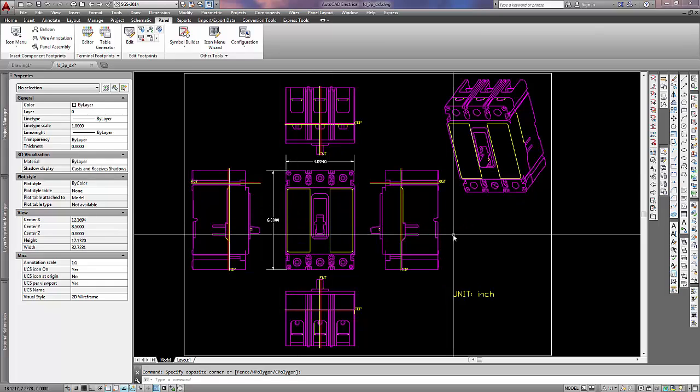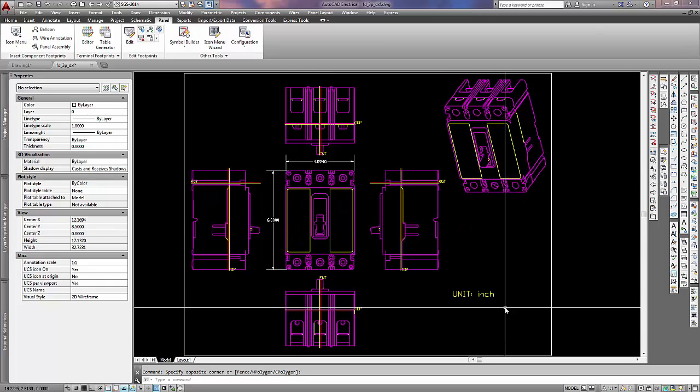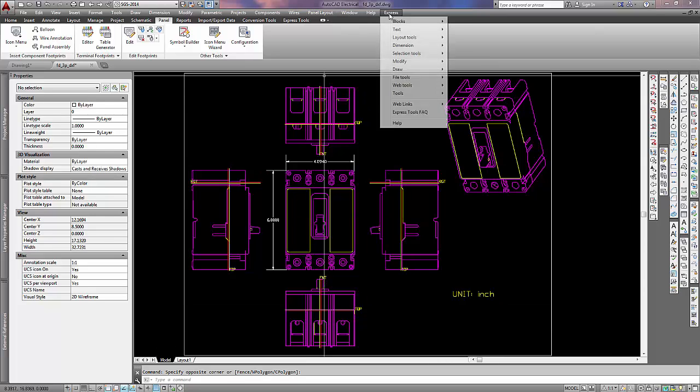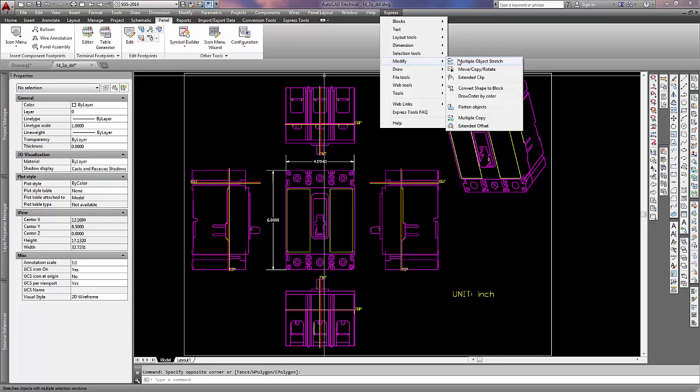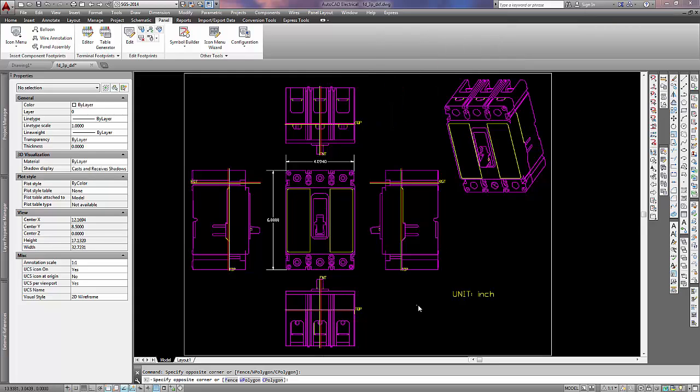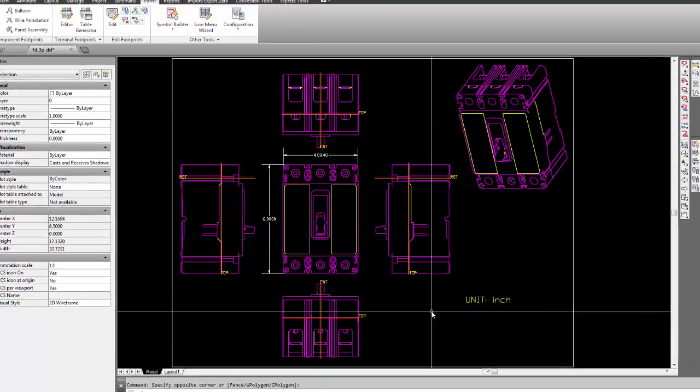You may need to scale your geometry because it was created in metric instead of inches, or you may need it to be in metric instead of inches. You may have to use the flatten command to make a 3D object into a 2D object. You may need to run overkill to remove overlapping and duplicate entries.